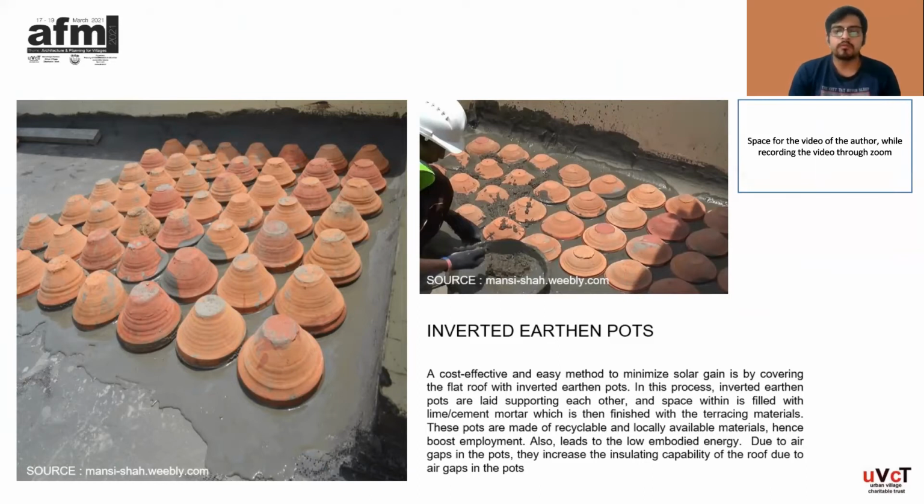These pots are made of recyclable and locally available material, hence they boost local employment. This also leads to low embodied energy. Due to gaps in the pots, they increase the insulating capability of the roofs, which leads to thermal as well as sound insulation. Let's move to the next slide.